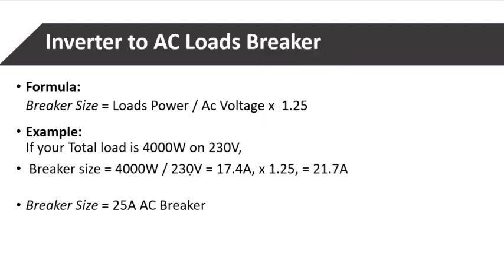So you should always take note of that when designing your system. Now another mistake is installing a DC breaker while you're supposed to install an AC breaker, or installing an AC breaker while you're supposed to install a DC breaker. That's a very wrong habit as an installer. Make sure if you are dealing with AC current, you are installing an AC breaker, and if you are dealing with DC current, make sure you are installing a DC breaker. Because your client will not know doesn't mean that you should go ahead and do it, because he doesn't know which one is AC or which one is DC.